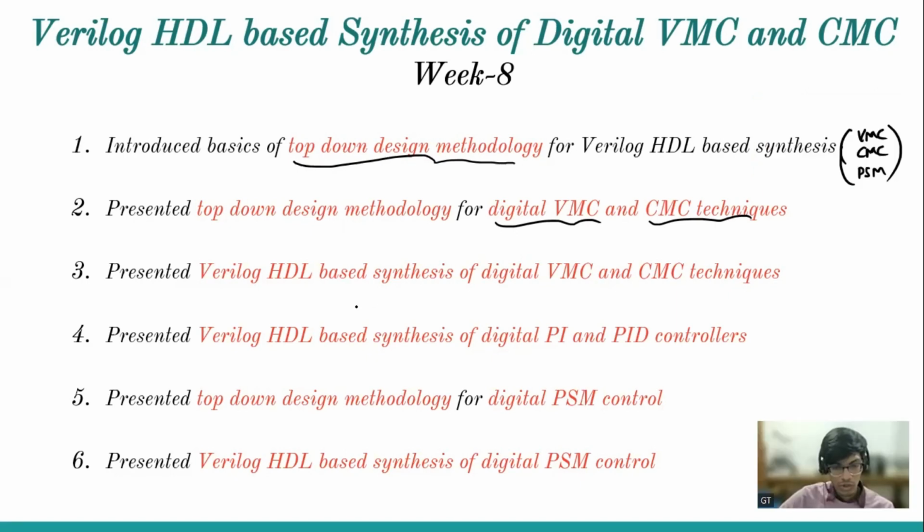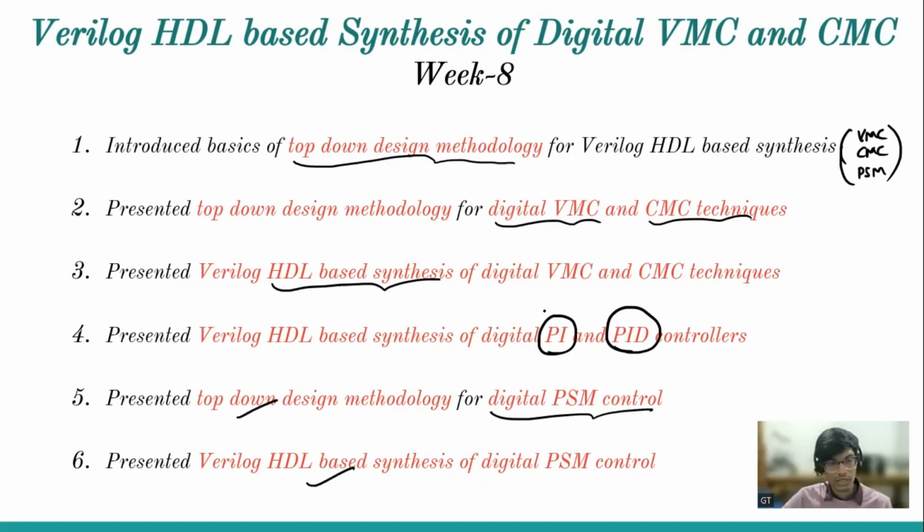Then we have also discussed Verilog HDL-based synthesis and how to design the PI controller as well as the PID controller using fixed point arithmetic as well as Q format in Verilog HDL. And then we discussed digital PSM control, the top-down design methodology, and also the Verilog HDL-based synthesis.